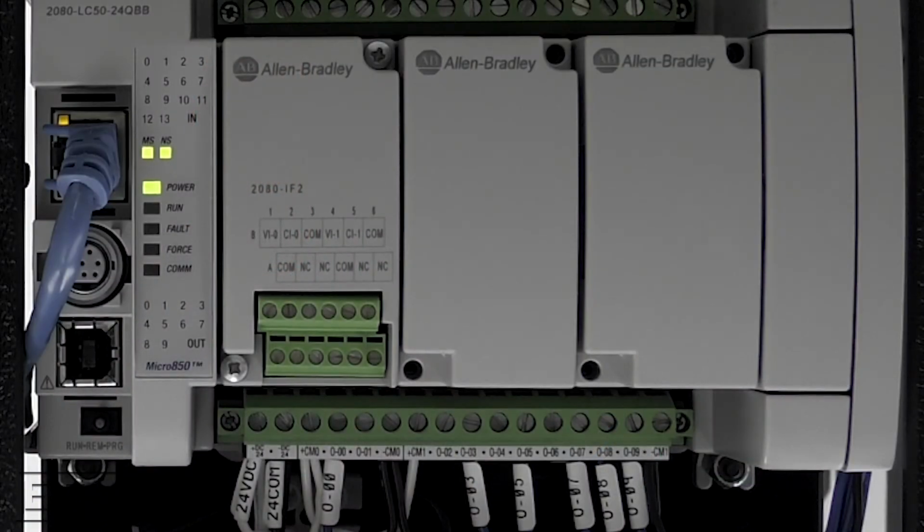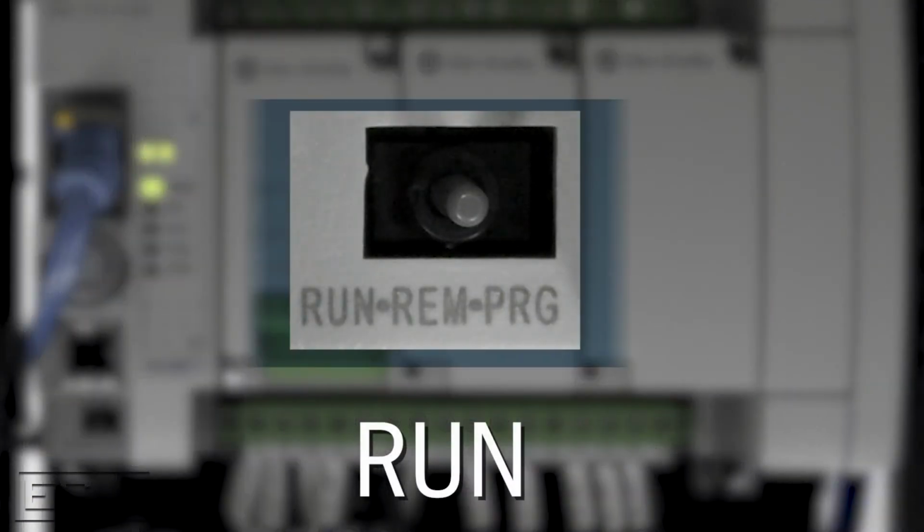The mode switch has three possible positions. The first position is run, which means the processor executes but no online editing or program downloads or firmware flashing is allowed. This is considered the most secure mode of operation since it can only be modified with someone physically